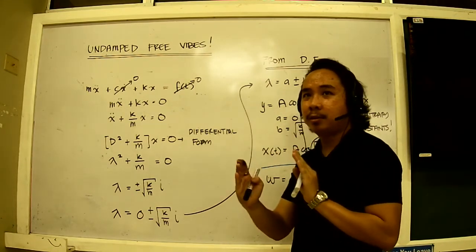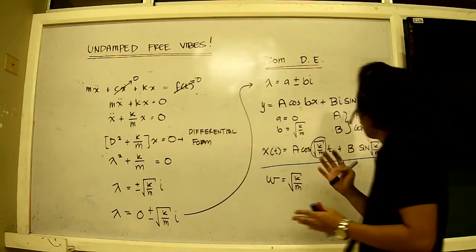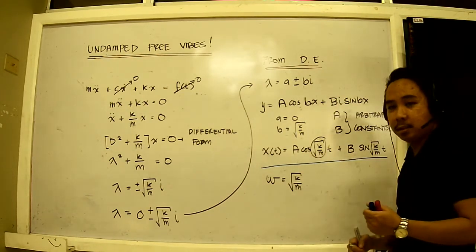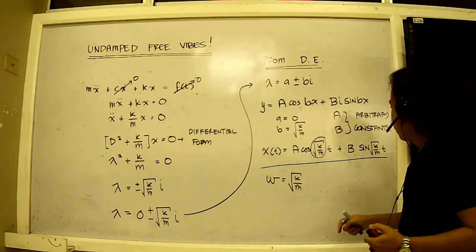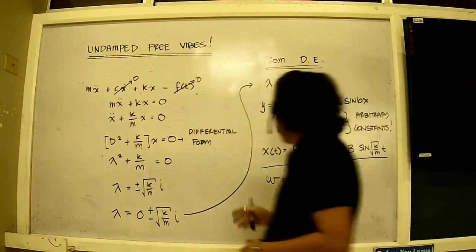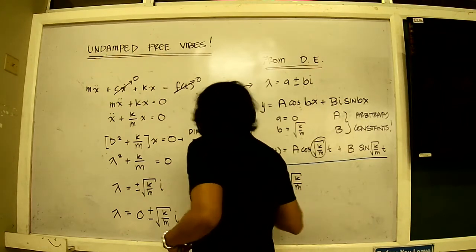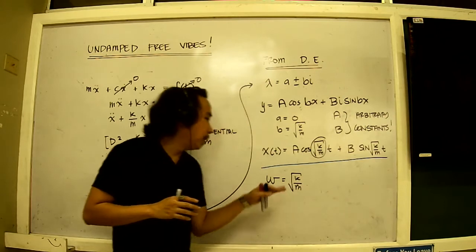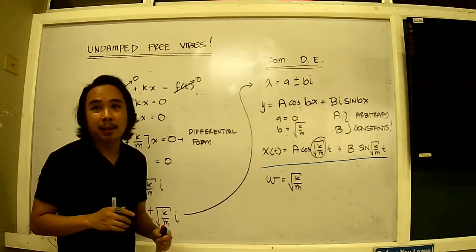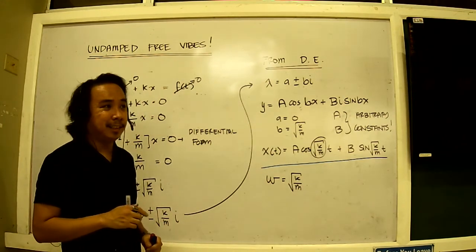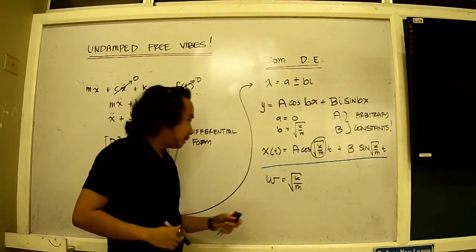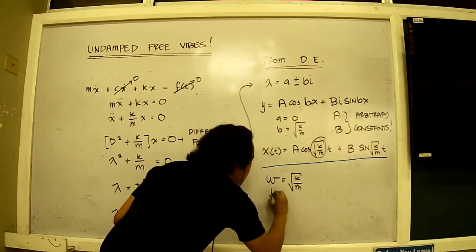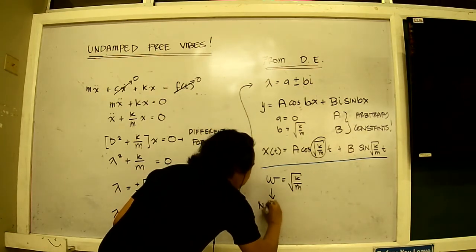So you can see why it is best modeled as trigonometric functions. With trigonometric functions, it oscillates and returns to its current position, back and forth, so it has a frequency and a period. I would like to define w as the natural frequency of this structure.